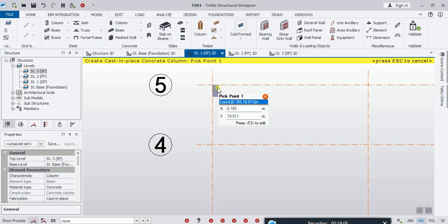Now if your grid is measured from center to center, in your plans the grids are measured from where to where? The distances in your plans are measured from where to where normally? Normally from center to center. So the column should be in the center or it should be at the edge? Should be at the center. Are we clear? But once again, it depends what you calculate exactly. Are you calculating the distances from the end to the end, or are you calculating center to center?